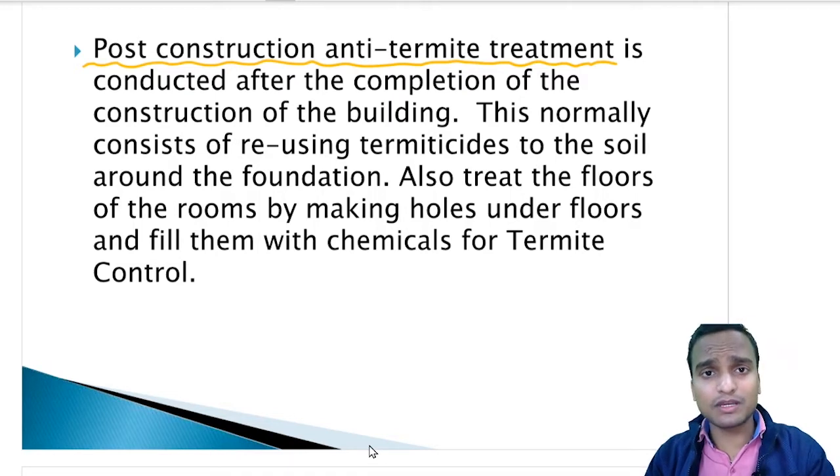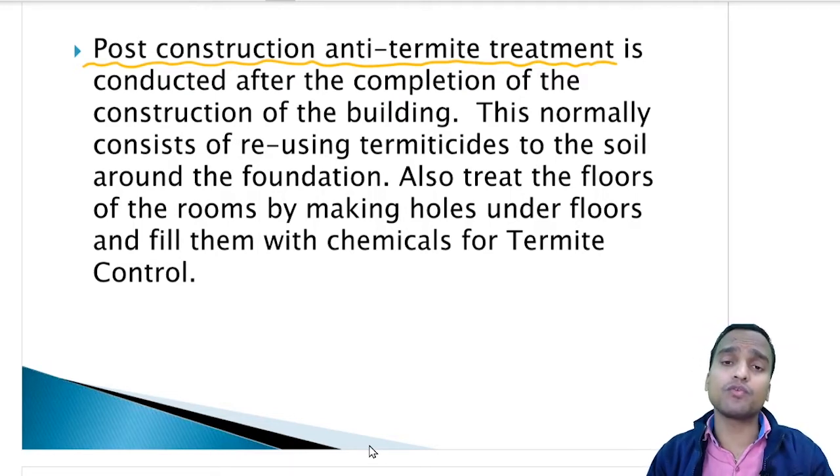Once one round of chemical application is done, we may go for a second round of application by those syringes into those holes. After doing that, we may cover these holes with white cement and refill them, which is also good for the external appearance of the floor.